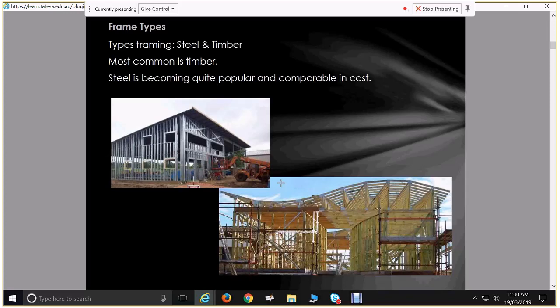If we're going to be working on a concrete slab, which is all nice and flat, it's actually a very simple thing to be knocking up wall frames on site because all of your studs are going to be the same height. So that's your vertical members in your wall frame. They're all going to be the same height. So you send your apprentice over, go, look, I need 18, 20 or whatever of these studs at this height. They're just chopping them away like this. And then you go laying it out on your floor slab, shoot some nails in, tilt it up.